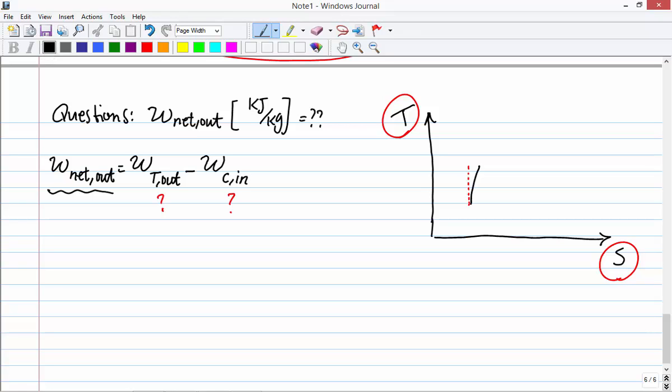Then pressure is constant because nothing is mentioned in the question, so just to make life easier, we assume that pressure remains constant in the heat exchanger. And once again, now we are in the turbine, and that is how the isentropic process looks, the curve, but now the entropy increases, so it ends up at a higher entropy. And again, we assume that pressure is constant in the second heat exchanger when the heat is rejected. Then we remain on this curve.